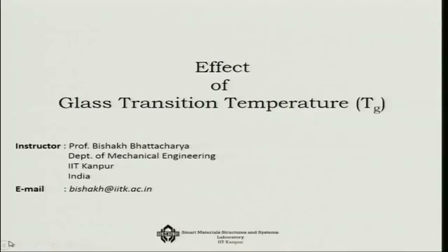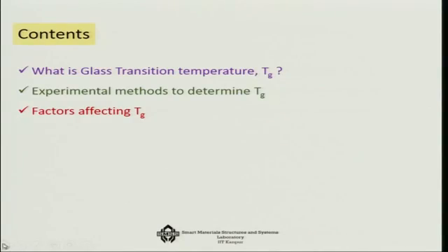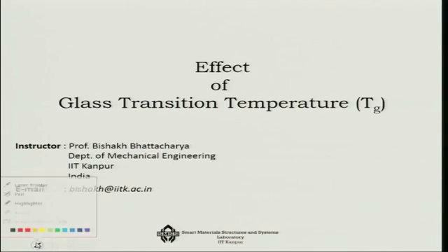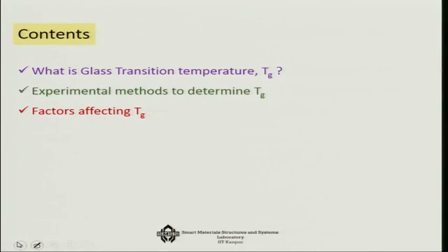In the last talk, we have discussed so much about the crystallinity and the amorphous nature of a polymer. The interesting thing is that with respect to temperature, the polymer can actually change its physical property in a very drastic manner, not unlike many of the other solids, and that important temperature is also known as the glass transition temperature of a polymer. So we are going to talk about this glass transition temperature because that is what is very important in terms of the nature of the polymers.